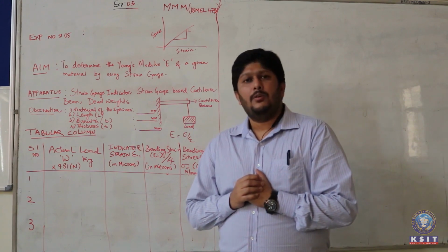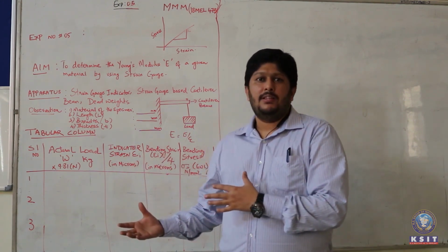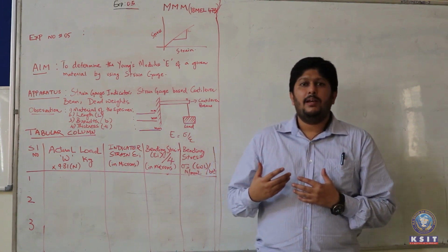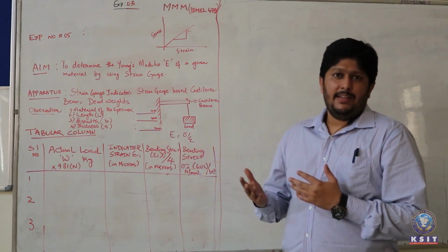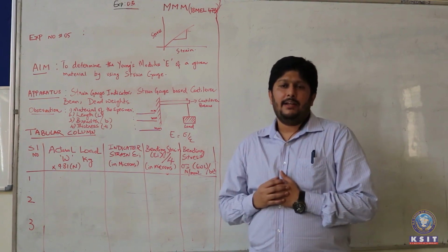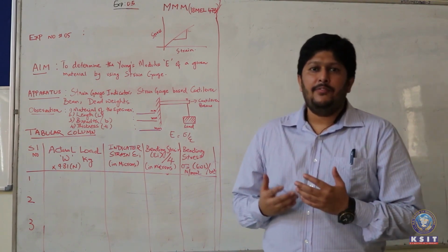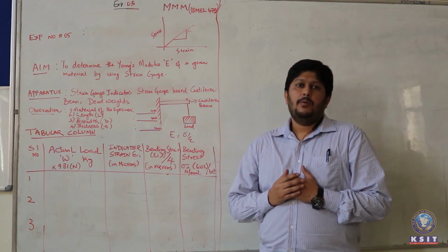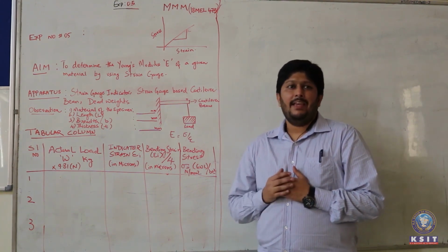In the olden days they used scales where you put weights on one end, put the material on the other end, and weighed it. Those technologies are outdated. Nowadays we use strain gauges. A strain gauge is more of a digital indicator where you put the load on a scale and the scale gives you certain readings. But how do you know whether the reading is correct or not? So you have to calibrate even strain gauges.